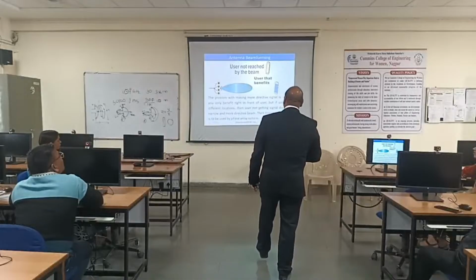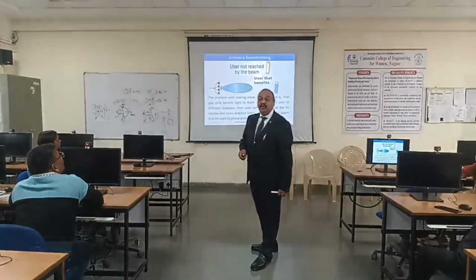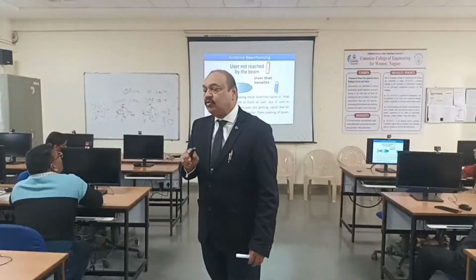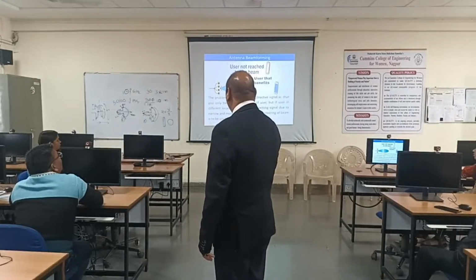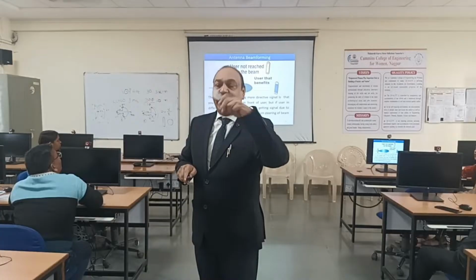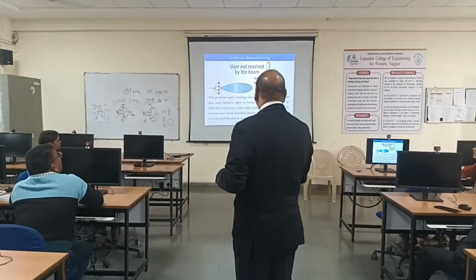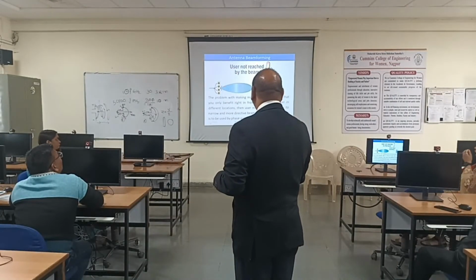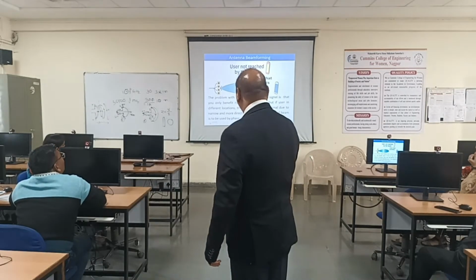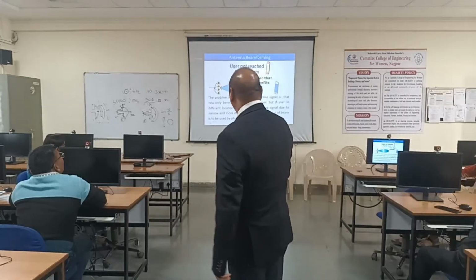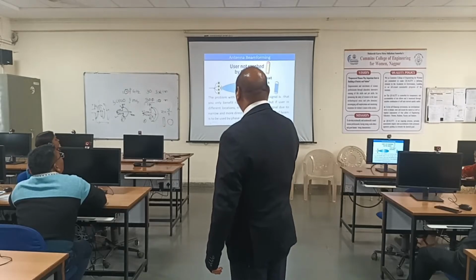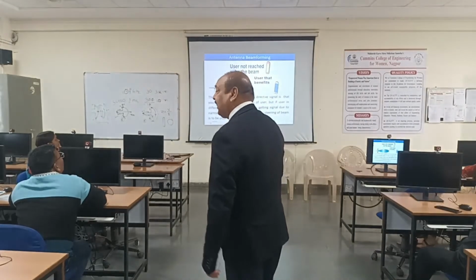So antenna beam forming has some disadvantages. The antenna beam is focused in a particular direction, that is the directive antenna. So gain will increase. If we made 4 elements, then gain increased 4 times. But it focuses only in a certain direction. If the user is here, the user will benefit, they will get good coverage, the beam can travel a long distance, even if the distance between the two is very large. But if there is another user not reached by the beam, another user is there, but the beam is not focused in that direction.